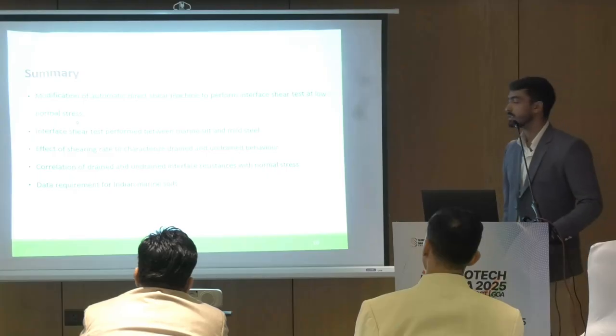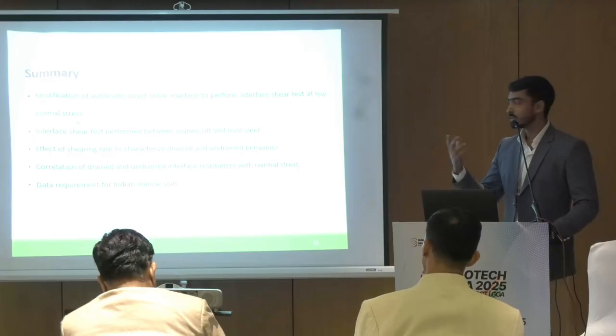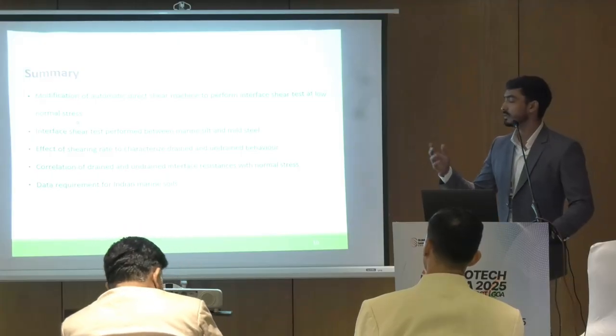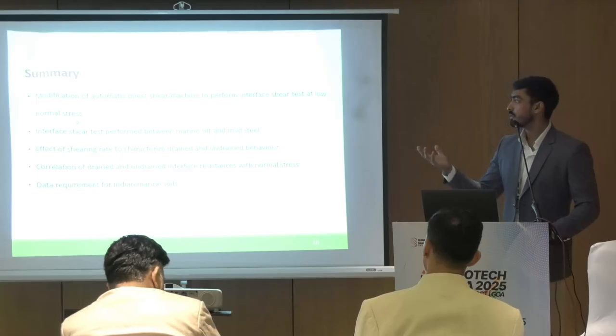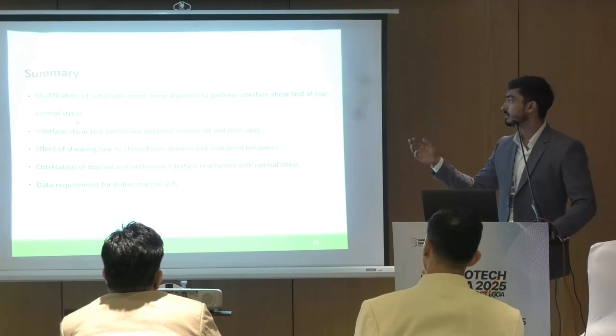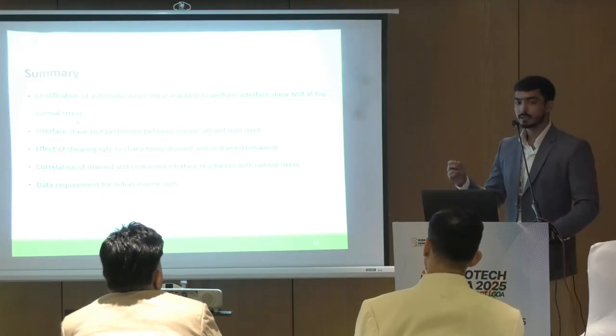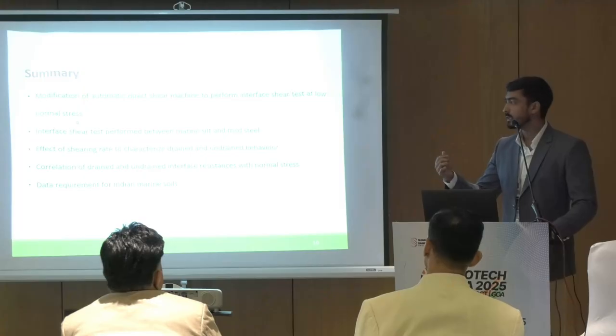In summary, I would say that we have modified automatic direct shear machine to be operated as interface shear machine at low normal stress. We performed a test, and we fitted our results in an equation so that we can characterize the results as drained and undrained behavior.